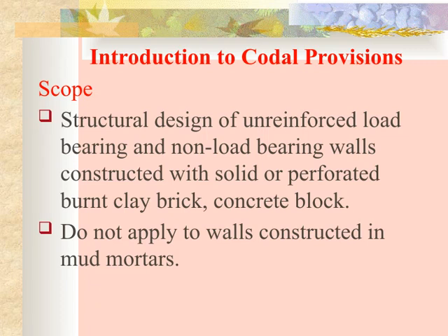Today, I'll be introducing you to the codal provisions, focusing on their scope and application. When it comes to the structural design of walls, these provisions specifically cover unreinforced load-bearing and non-load-bearing walls. These walls are constructed using materials like solid or perforated burnt clay bricks and concrete blocks, which are common in many building practices. It's important to note that these provisions do not apply to walls built with mud mortars, so if you're working with traditional or earthen materials, different guidelines would be necessary. Understanding these distinctions helps ensure we're applying the correct standards for safety and durability in our projects.